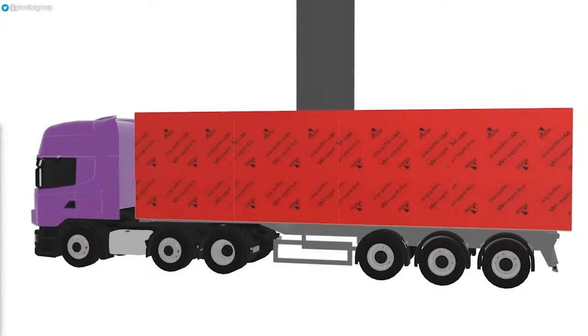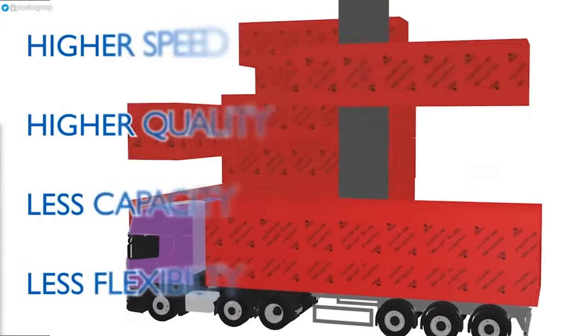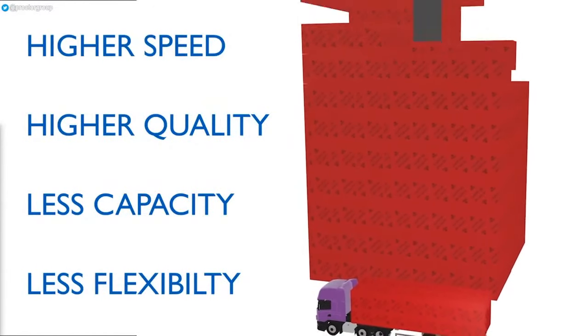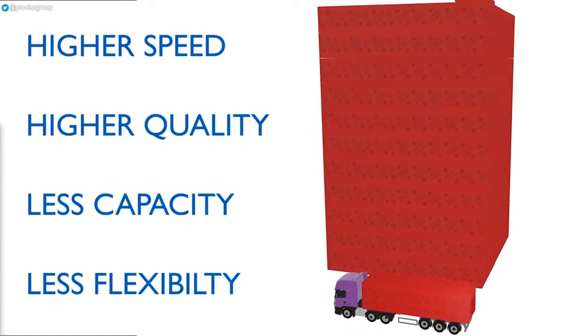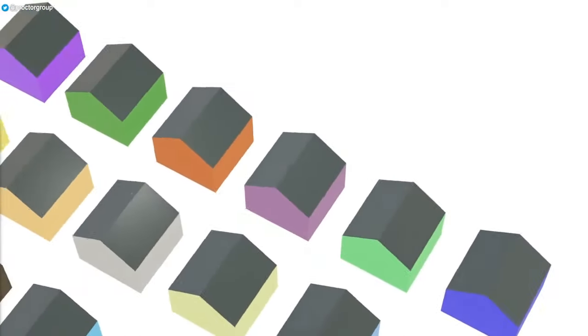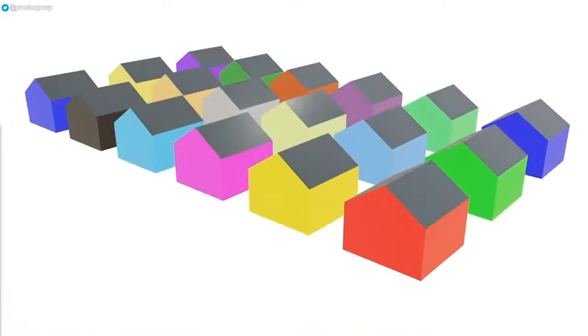As with CLT though, there can be issues with bottlenecks in the supply chain and scalability owing to the relative newness of this type of construction and a correspondingly lower number of suppliers. It is also very difficult to accommodate late changes and adjustments without substantial cost and time penalties. Another particular challenge for architects when using modular construction in housing is to avoid uniformity and repetition in design. Careful consideration of cladding choices and building layouts is therefore necessary.